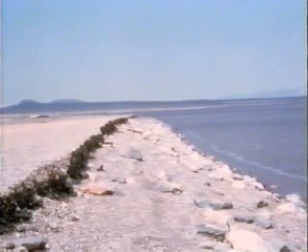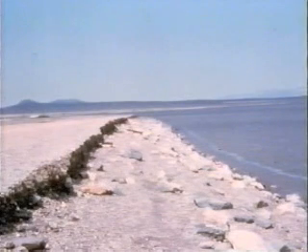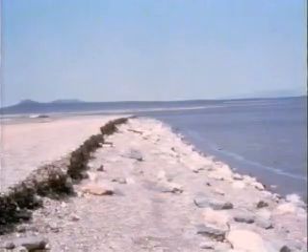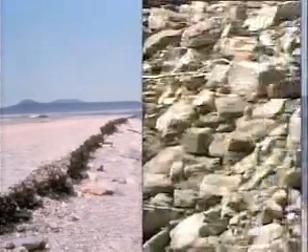This eroded area lessens the width and possibly the height of the embankment and could lead to increased seepage or overtopping of the dam. The reason that the riprap failed and that beaching occurred is that the riprap was undersized. You should be continually on the lookout for undersized riprap, since this condition will likely result in beaching in the future.